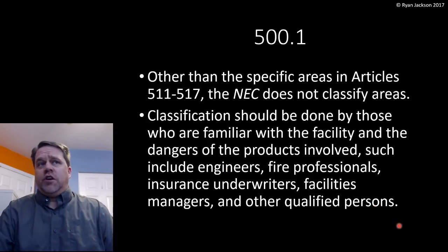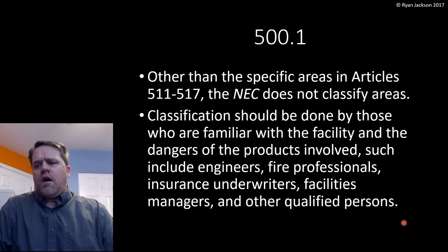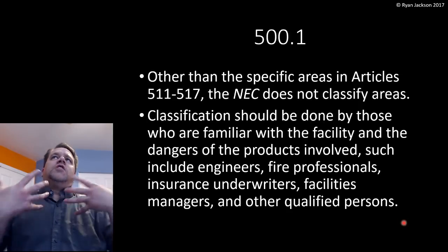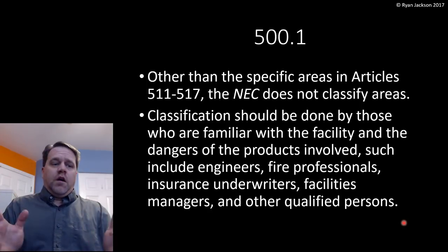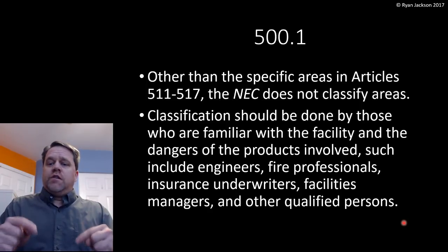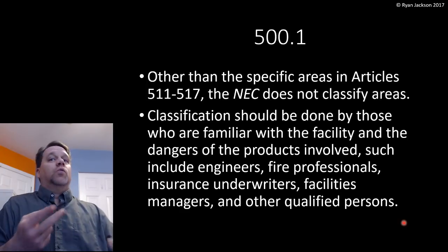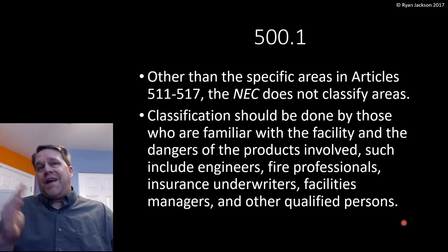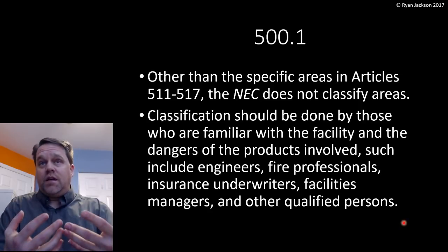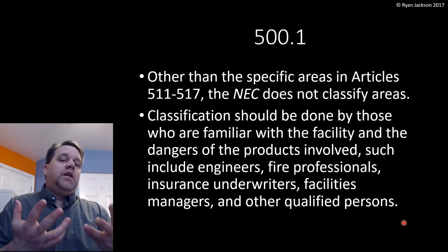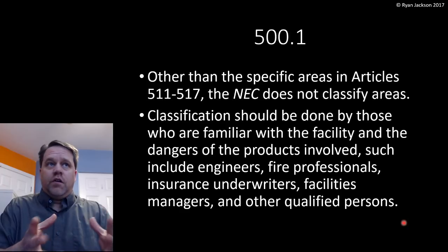I need mechanical engineers, not just electrical engineers, because I need to know how much air is in that facility, right? What's the cubic feet of the space? How much ventilation do we have naturally through windows and doors? How much mechanical ventilation do we have? How much mechanical ventilation do we need to dispel all of the vapors and gases that are inside of the area?